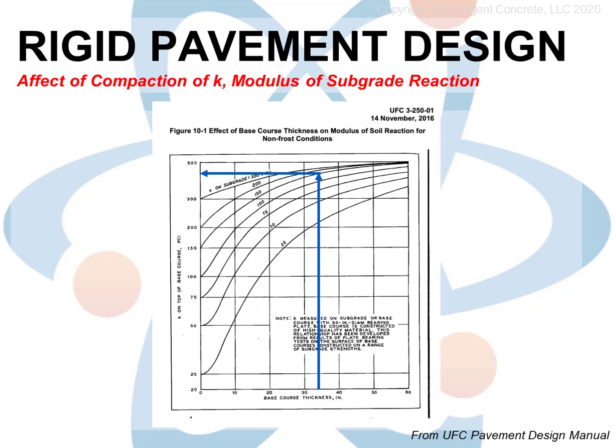Our soil has a K of 150 PCI, an assumed value based on these tabular values typical of the soil type. Find along the left side the number 150 and you'll see a curved line coming off of it. Go along the bottom to 34 inches and then go up to the 150 line. You'll see that our K has been increased to perhaps 400 PCI or thereabouts. Remember this number for about 15 minutes. We'll be using it later.